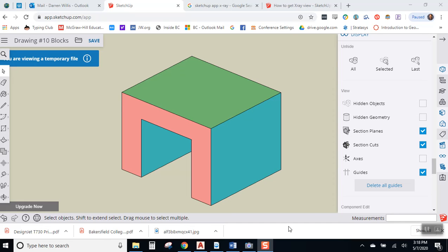All right, very good. For your next trick, I would like you to set this object up using multi-view drawing with orthogonal or orthographic projection, just like we've been doing, and try to keep in mind that there might be some hidden lines involved in this, okay? So try to visualize what you would see from the front.